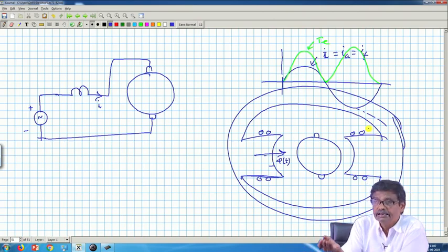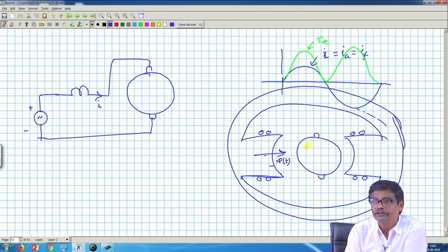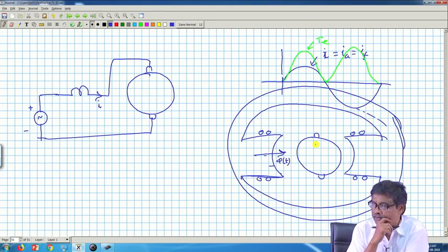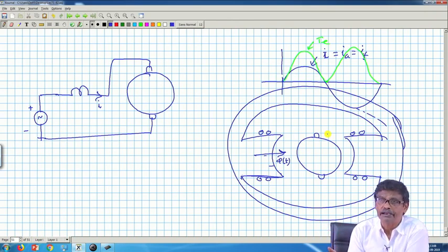In the armature, in any case, even in DC operation, eddy current loss and hysteresis loss take place, and that is why the armature is laminated in a normal DC machine as well. Remember this fact. For a DC motor which is to be operated from DC supply alone, if you insist on that, then use solid iron for the stator iron structure, no problem. Of course, the armature is to be laminated.